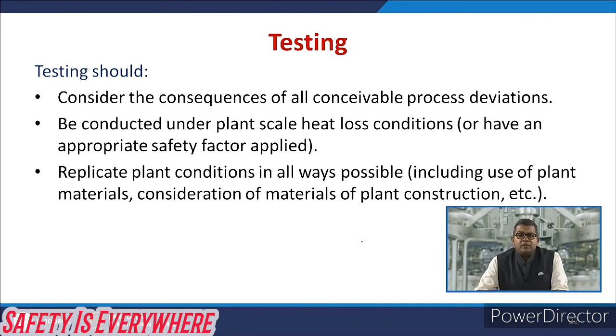So, let us think about the testing. This testing should consider the consequences of all conceivable process deviations. This should be conducted under the plant scale heat loss condition or have an appropriate safety factor applied. This should replicate the plant condition in all ways possible, including the use of plant material, and consideration of material of plant construction, etc.